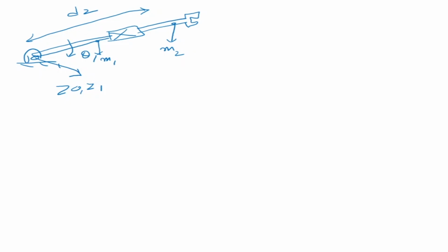When we found the kinetic energy and the potential energy, we found something very interesting: joint number 2, although it's a prismatic joint, that means it moves like this, is subjected to linear velocities when the previous joint rotates. That is something we found interesting: in the dynamic equations the velocities propagate from joint to joint.